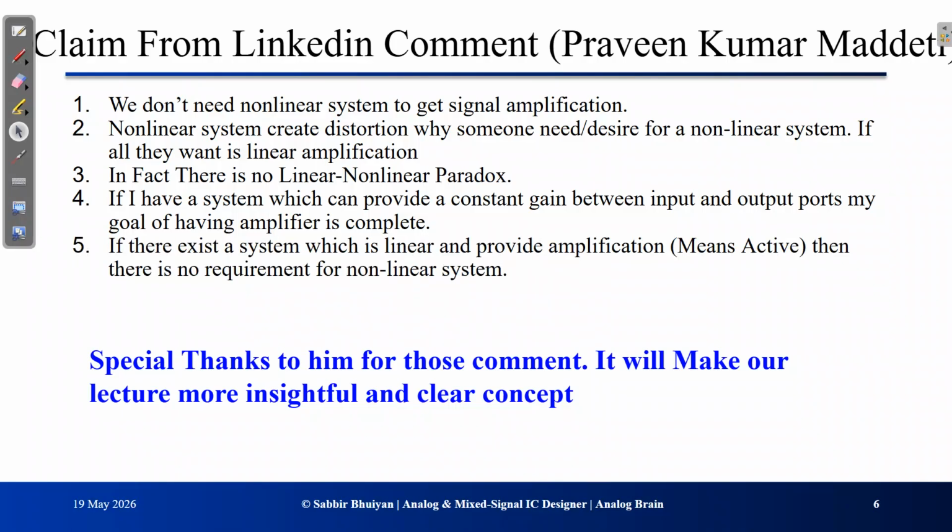Number five, if there exists a system which is linear and provides amplification, meaning he's supposing this is active, then there is no requirement for a nonlinear system. He's actually right. If you have an active element and this is linear, you will have power amplification. You don't need to transfer power from VDD to signal frequency.